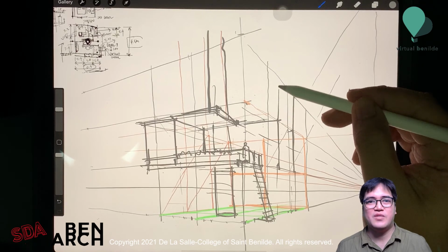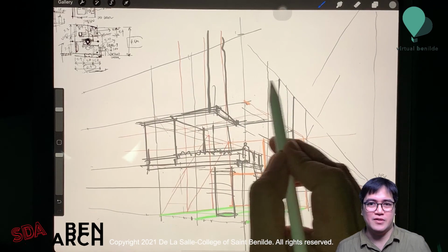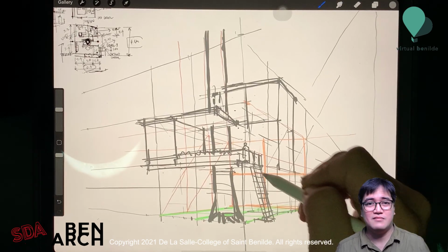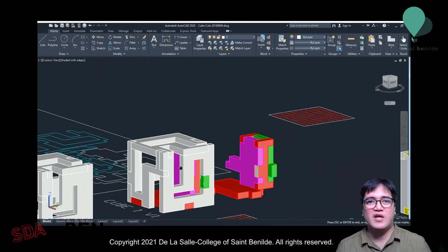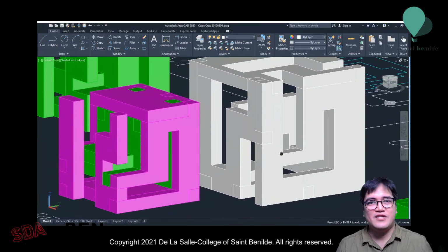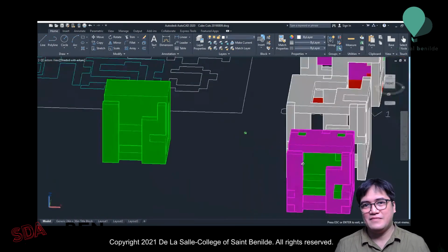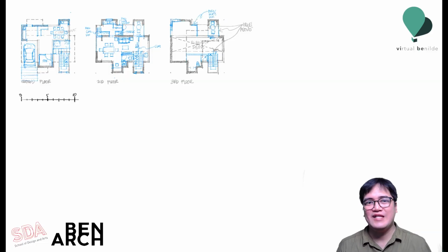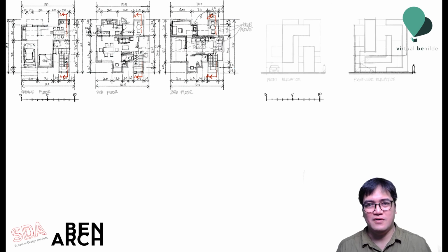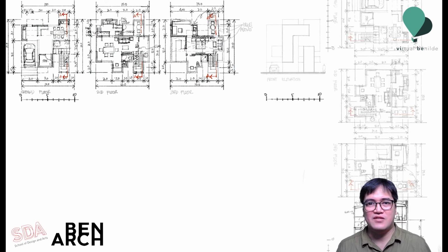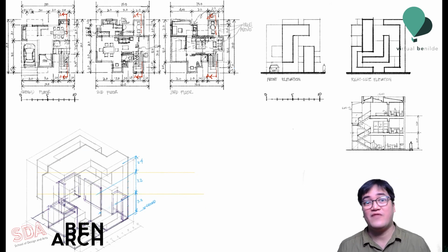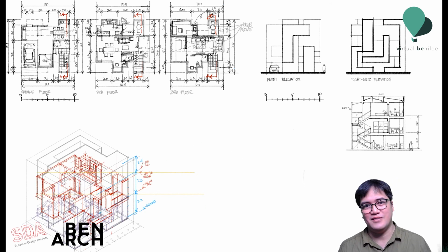You can't measure perspective drawings with a scale ruler to give you the information for depth or width or height on paper. Working with digital 3D programs helps in understanding during the design phase, but then you will need to supply the orthographic drawings eventually: the floor plans, elevations, sections, detailed drawings, and engineering details, with all the specifications to help quantify the materials and building methods.